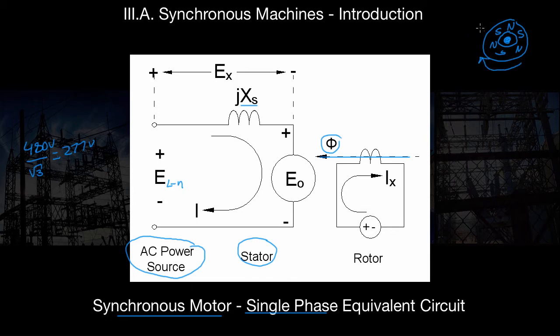As soon as you apply that voltage, which we'll call E, on those stator coils, you're setting up a magnetic field. It rotates in relation to the frequency of the power. Now that rotor is going to start spinning with it because the rotating poles are attracting it magnetically. Typically once that rotor is spinning up to speed, that's when they turn on their excitation power, or VDC. As soon as they turn that on, we have poles created in the rotor that instantly lock into place with the stator. So where you have an S on the stator, you'll now have an N for the rotor.